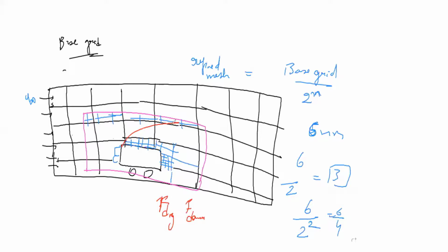So there it is going to have a boundary layer where there will be a gradient. Velocity gradient, pressure gradient, and all the gradients will be there in this boundary layer only. Outside this boundary layer, everything is U infinity. Agree? Yes, sir. So if I want to capture this, I have to capture this boundary layer, correct? Now the boundary layer has multiple sections. It has a log law region, a turbulent region, and a laminar region.